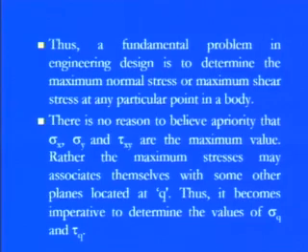So the first aim in any component design is to know what the maximum stress is and at what point these stresses are acting within the object. And there is no reason to believe that sigma x or sigma y or tau xy are the maximum values. If you are talking about sigma x or sigma y, they are simply the normal stress components.